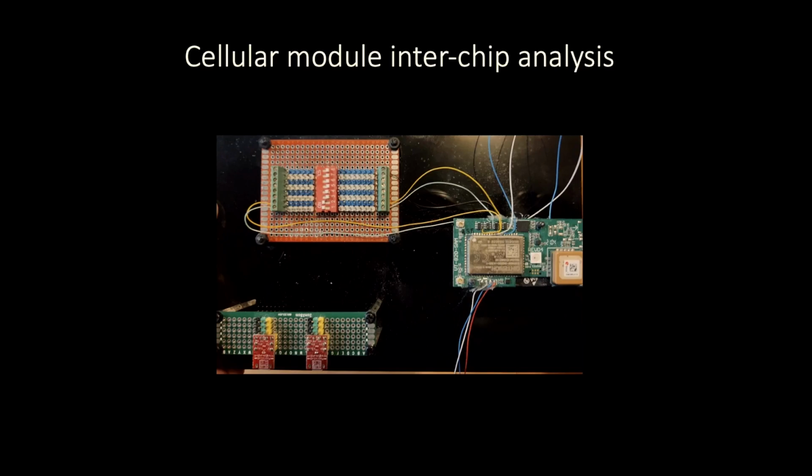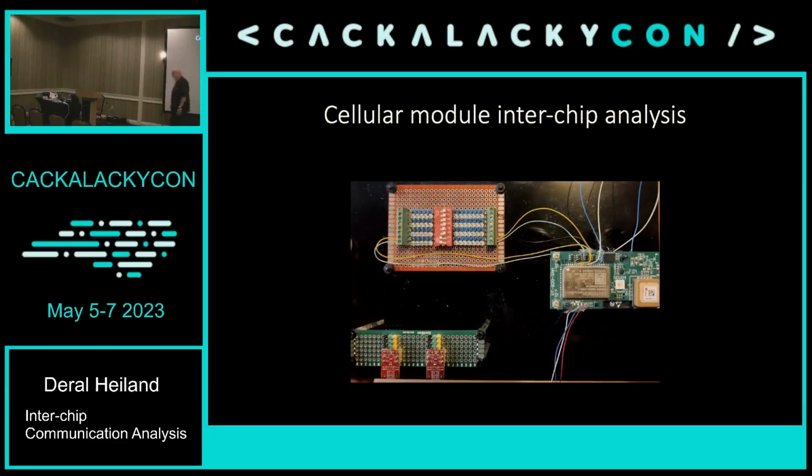One side's 3.3 volts, the other side's 1.8, which really screwed me up. In this case, I literally had to cut into the circuit boards to find the runs in multiple layers and remove chips to get access. So that was kind of a crazy example.